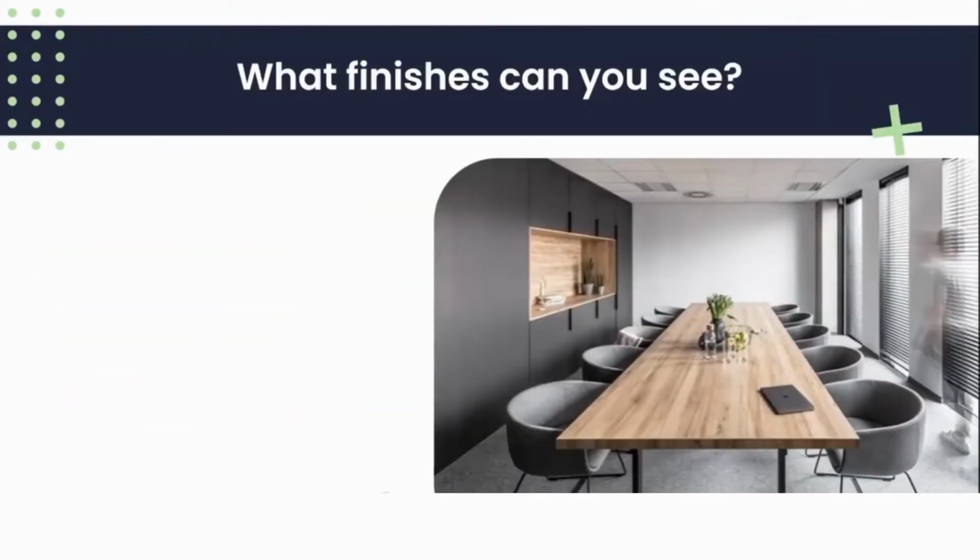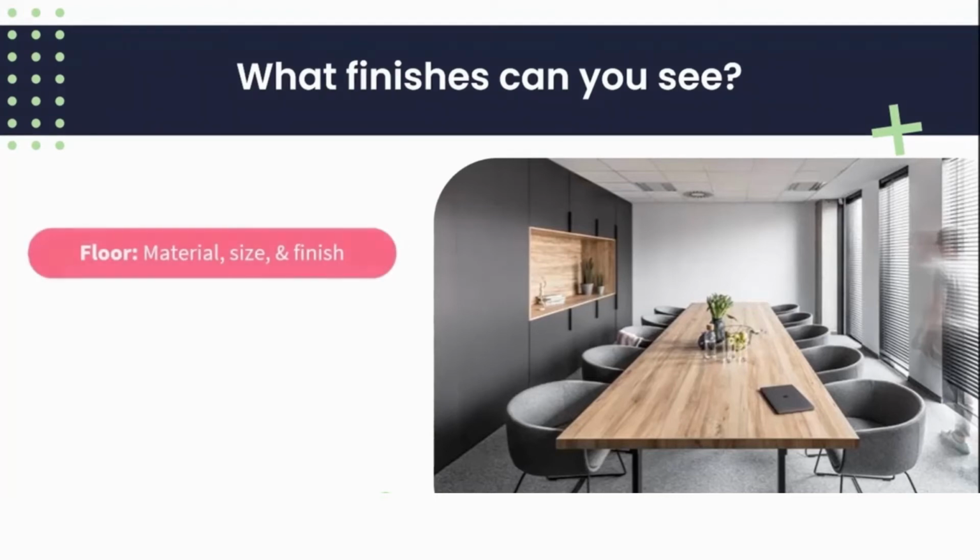Let's see if you're all following as we try an example for a second. Grab your sketchbooks and let us create a rough finishing schedule. You're going to use this room on your screen as an example, and we're going to break it up into 3 main headings as we look at the finish relating to those headings. You are going to then populate those headings with finishes associated to the image. We're going to start off from the bottom and work our way up, starting with the floor.